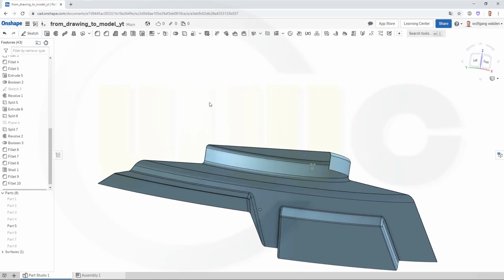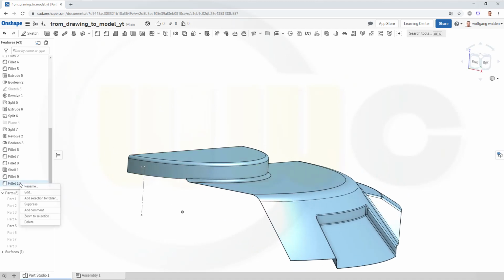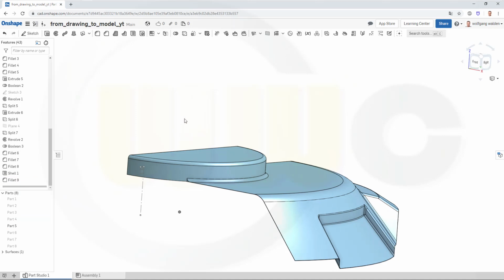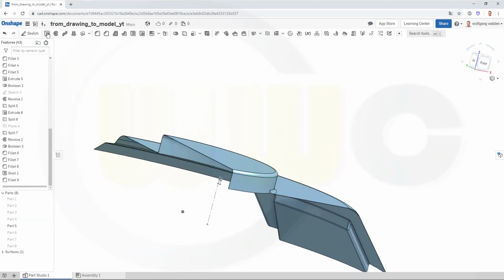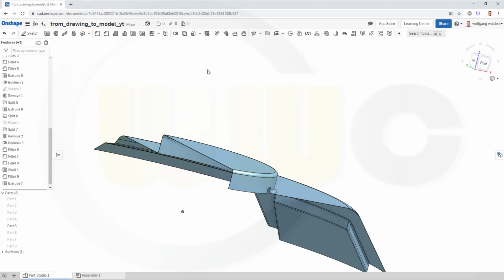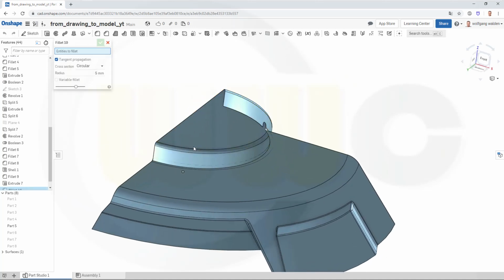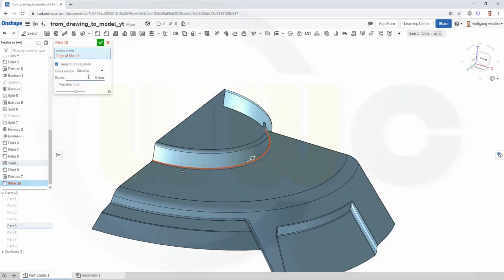And that seems to have moved this up, and that's no good. So I have to do this later. I have to do that extrude first. And let's remove this one here and confirm. Now I should be able to do that fillet. So go for that edge here and make it 1.05 and confirm.